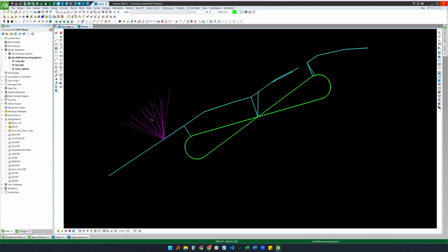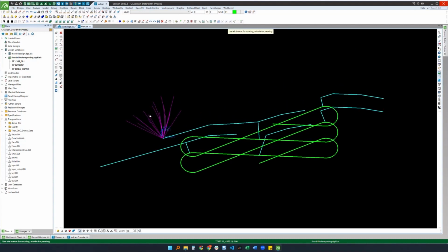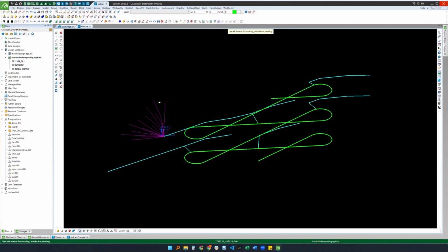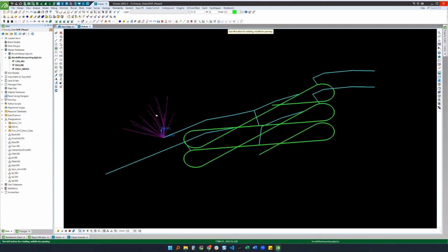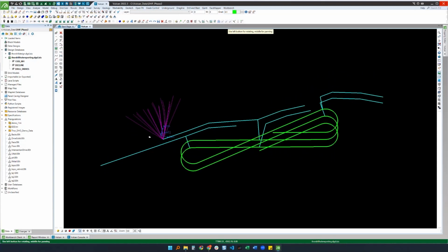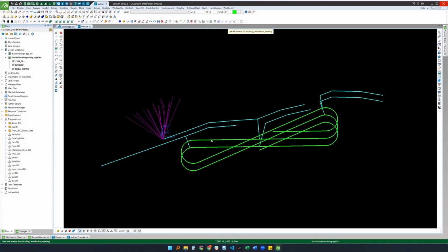And you'll notice I've applied deviation to these holes using deviation rates that I calculated from historic drilling using the deviation calculation manager. So one of the biggest hazards in drilling, especially underground, is potential interactions with existing development, stopes, voids, drill holes, or even services. And historically, checking for these interactions was a fairly manual process. So we made this tool to create an automated and repeatable way for you to do this quickly in Vulcan.